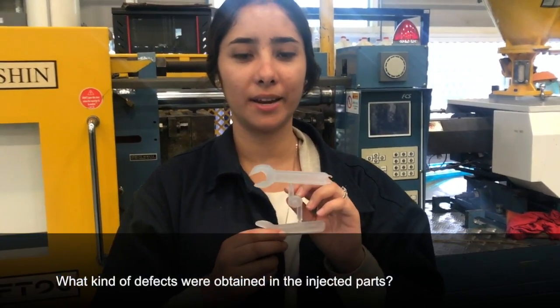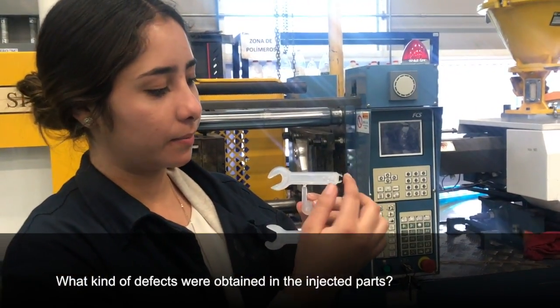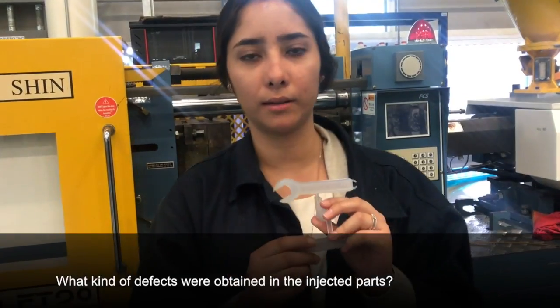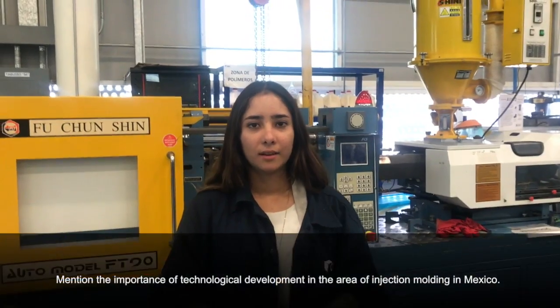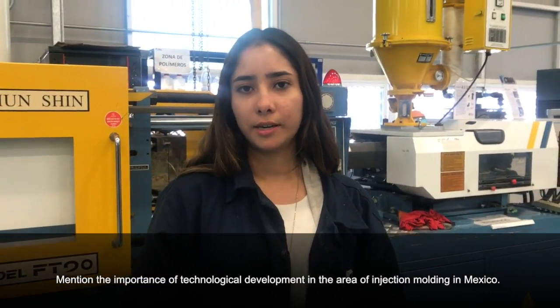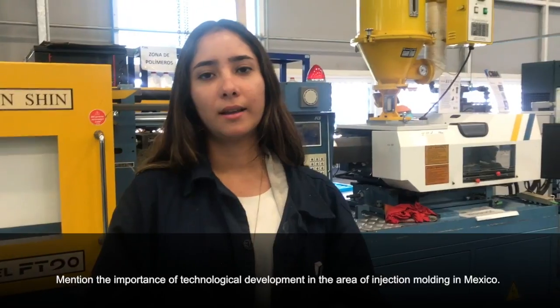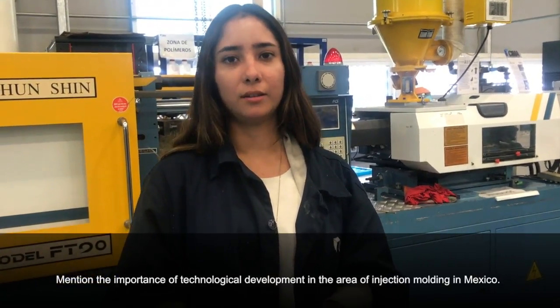So in the first injection that we made, we obtained these bubbles, an incomplete piece because we didn't calibrate the machine well with the right speed and pressure. So the plastic injection is a very useful and important process here in Mexico because you can have a mass production which is very cheap and also to recycle the plastic.